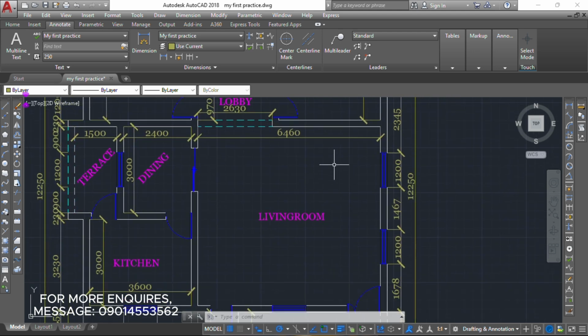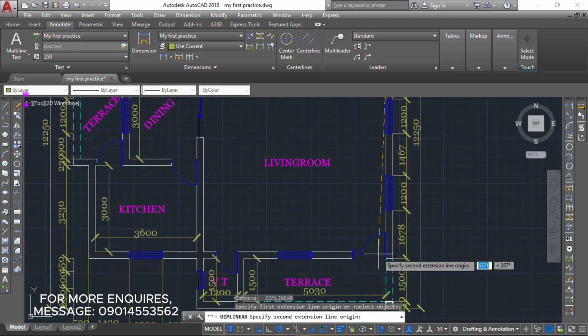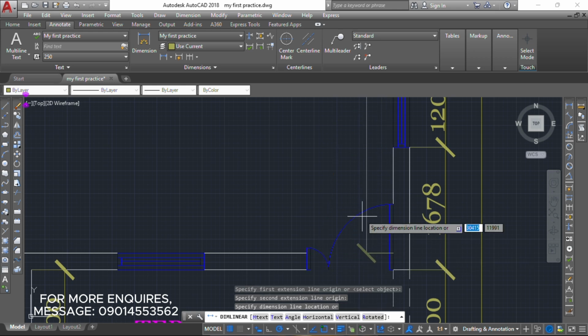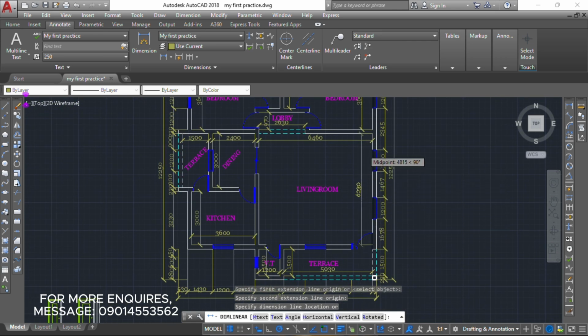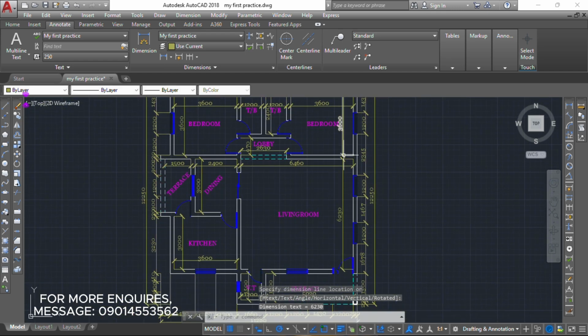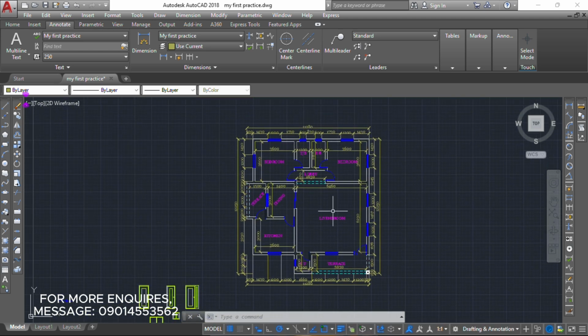So that's part of the little changes that might occur. Let's go ahead and check the length here also. This is where our internal wall is stopping. So just go ahead and select it. You see this also is increasing a little bit with a measurement of 230. In this case, we're having 6,000, right? But here it's giving us 6,230. So that's not an issue since it's not changing any major component in our plan, right? So we are still good to go.